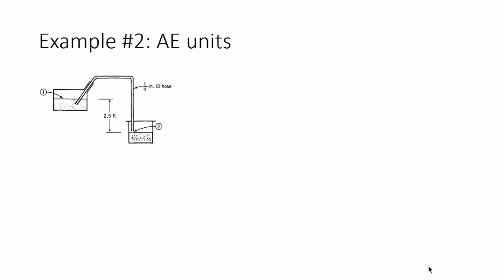The general mechanical energy balance would be delta P divided by rho plus delta U squared by 2 plus G delta Z plus F cap equals minus Ws dot divided by m dot. So, here we have been told that the pressure at point 1 and point 2 are both 1 atmosphere, which means delta P would be equal to 0. We also do not have any moving parts in this system, which means shaft work will be equal to 0.